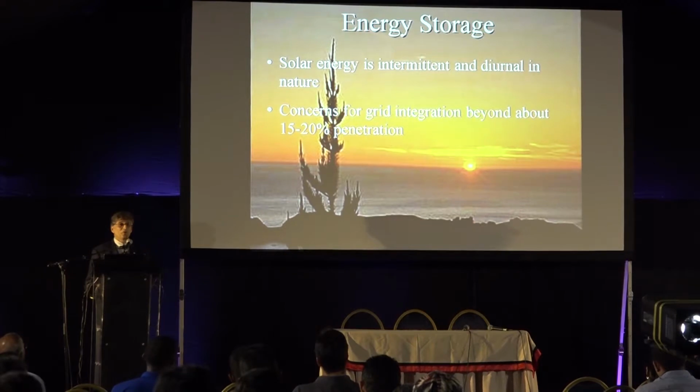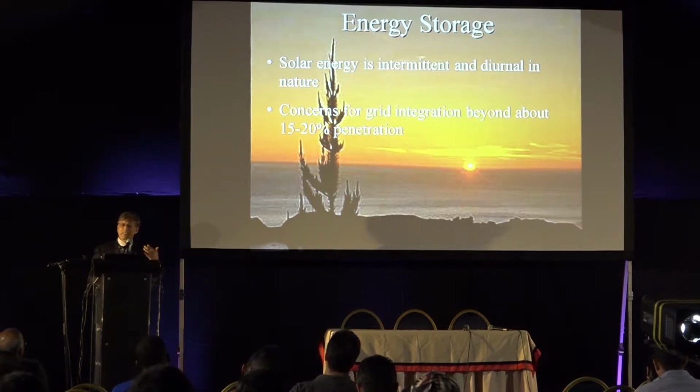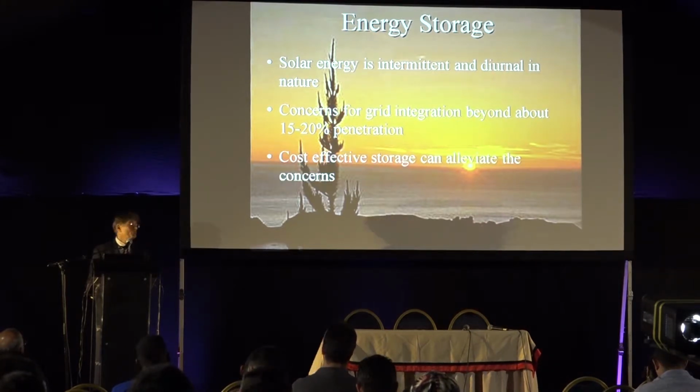And there's more, that if solar energy, or for that matter, wind energy, gets up to about 15 to 20% penetration in the grid, that's when the intermittency of the resource becomes a real big problem for the grid. So that makes the grid unstable. So we need to, or we have to have energy storage at that point.